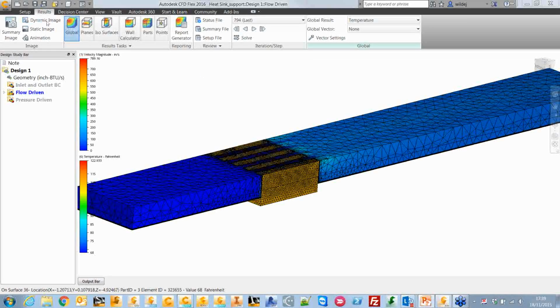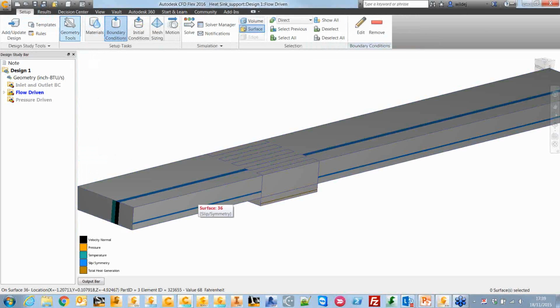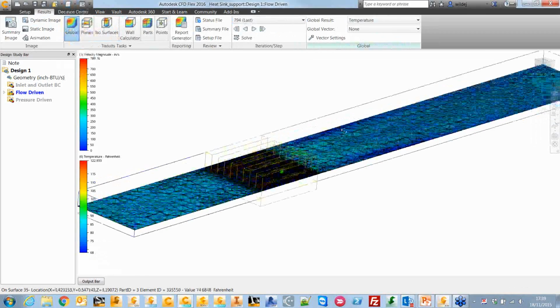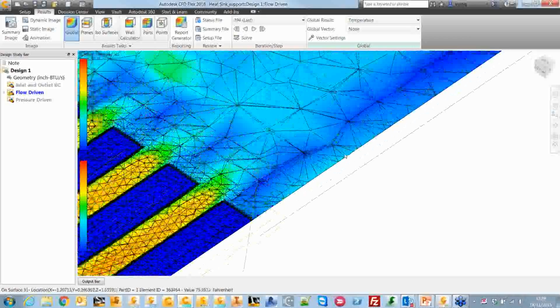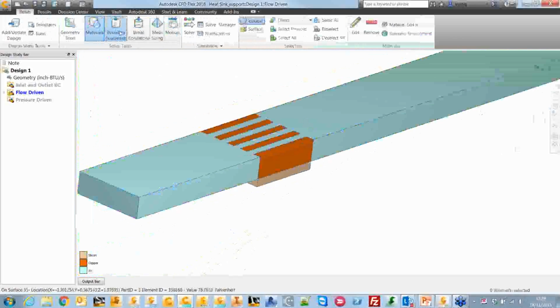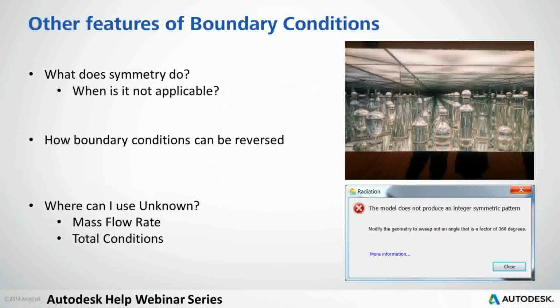What wouldn't have worked is if you take a look at my boundary conditions, I have slip symmetry on the walls already. And the reason for that is because I don't want friction on the walls. So the friction has been, or the boundary layer has been removed, so there's zero friction on the walls. And that's fine. But if we enabled radiation with all of these symmetry walls, which would act like mirrors to radiation, we would have something pretty similar to this image here. And you would see the error at the bottom. So it kind of repeats infinitely, and you would have some issues.